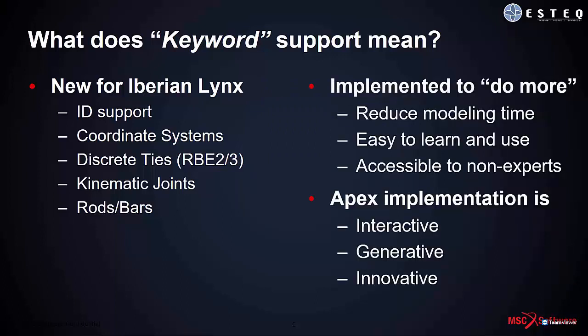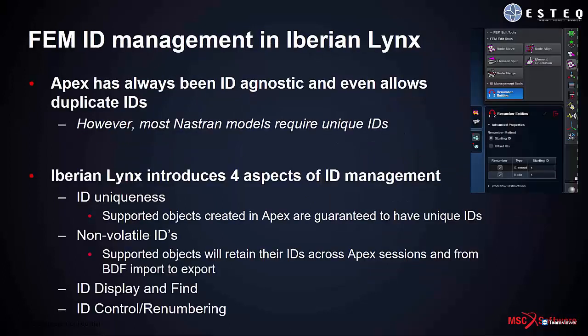The whole focus of this is to support more modeling with Nastran, or simulation with Nastran. Obviously, it allows you to remotely solve while you continue in Apex, even though the plan is for Apex to be able to solve with its own solver remotely as well. That's not yet possible, so you can use Nastran remotely while continuing in Apex, and it uses fewer tokens. The other advantage is that you benefit from all the capability inside Apex for your pre-processing, and you don't lose any of your models that you have maybe in your library.